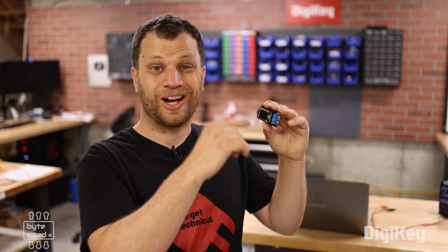There's so much more that this custom PCB can do. If you remember looking at the schematic, I also added power measuring circuitry to the load side. That allows me to measure the power coming from the panel and then the power going to the load, and if I compare those two numbers, I can calculate the efficiency of the charge controller. I also added separate terminal blocks for the battery as well as the load, and then on the load side, I can control whether that load is turned on or off with an additional MOSFET. That means I can have both a 12-volt battery and a 12-volt load connected to the charge controller at the same time, and I can turn the load on or off as needed.